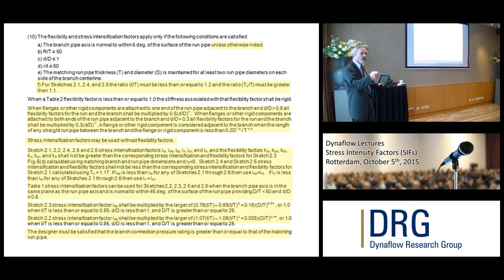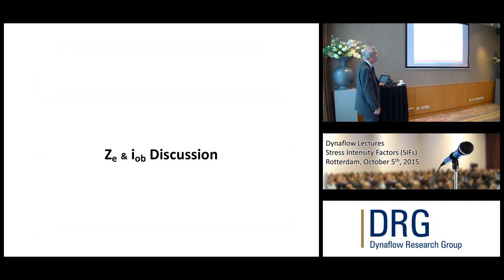So what will happen is all of your bends now will get about 20% stiffer. But your bends are off anyway, and that's not something we even had time to change. The effective section modulus that's used in the code won't be used anymore. So you've got to make sure that when you take a new I factor, you don't use it with any calculation that's going to use Z sub E.